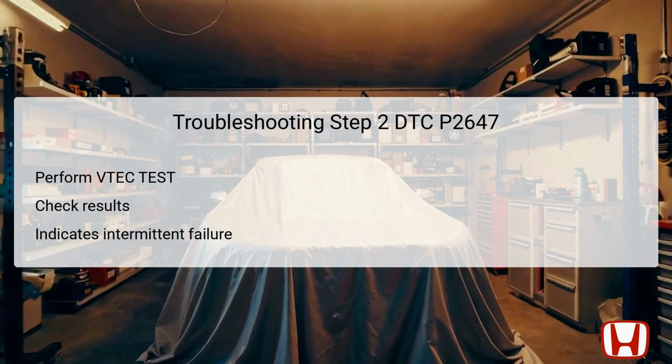Should the test yield an okay result, this suggests that the system might be experiencing intermittent failures, and attention should be given to inspecting the connections at the rocker arm oil pressure switch, rocker arm oil control solenoid, and the PCM. Collecting freeze frame data from the HDS could provide key context when patterns and failures are observed.